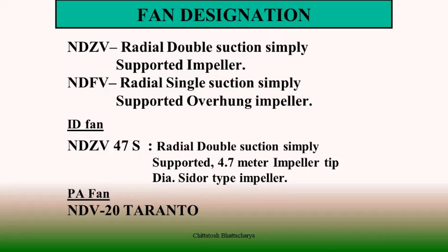And if we see the radial fan impellers, they have the impeller eye and shroud rings, and there may be a center plate, and blades are fixed in such a way that they are welded completely with the center plate or suction shroud rings. And there is an impeller shaft.